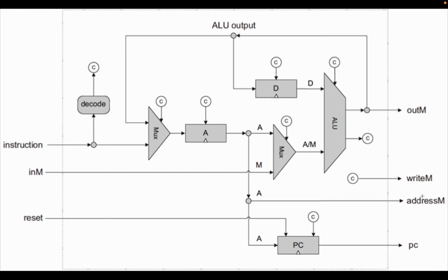It consists of input control bits such as zx, nx, zy, ny, f and no, which are indicators of the function that is applied on the two inputs to produce the output. The output control bits such as zr and ng determine the properties of the result.